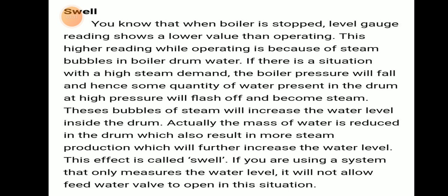If you are using a system that only measures the water level, it will not allow the feed water valve to open in this situation. With only one measurement, the water level, the system cannot identify the need to open the feed water valve.